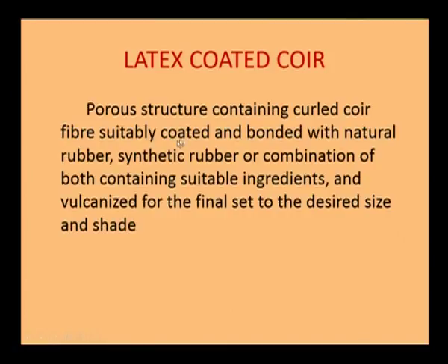So, you take the coconut fiber, you clean it thoroughly, then you mix with our latex rubber, then you add some other additives. Not only the basic thing is mixed together, but you should add some other additives. Mainly you need to compound it, you need to vulcanize it, then you are going to press it and make it into a desired shape for various products.